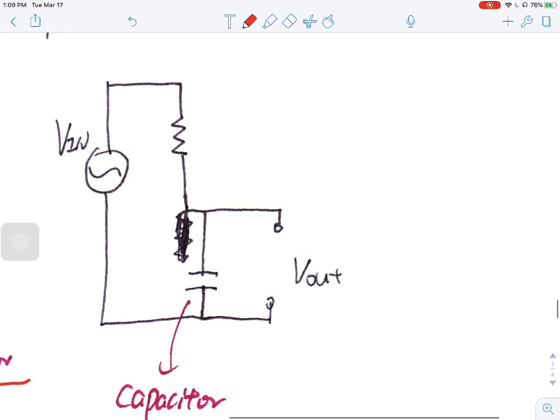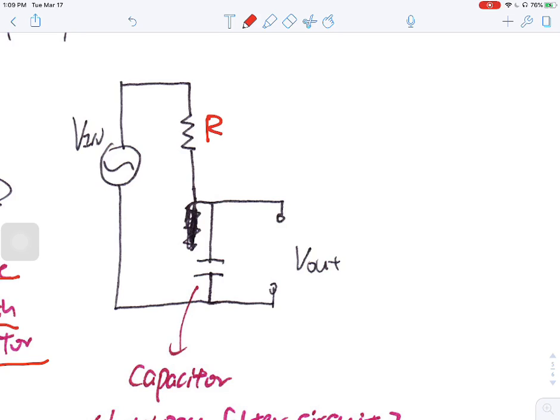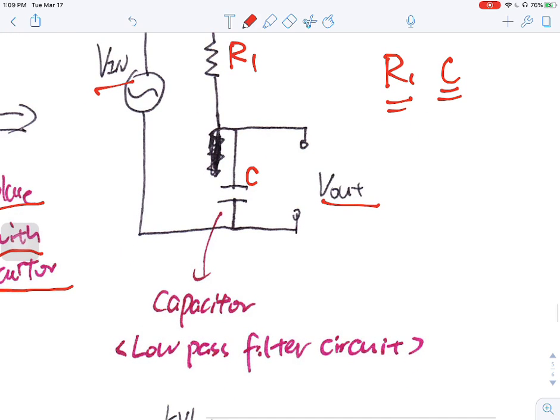So it gets rid of I2, R2, this is R1, and it adds a capacitor here. You still have the V in and V out, and that's the most basic low pass filter you can build. However, you may have the question, how do I decide the value for R and R1 and C? That really depends on the particular application you have. We're going to mention that later.